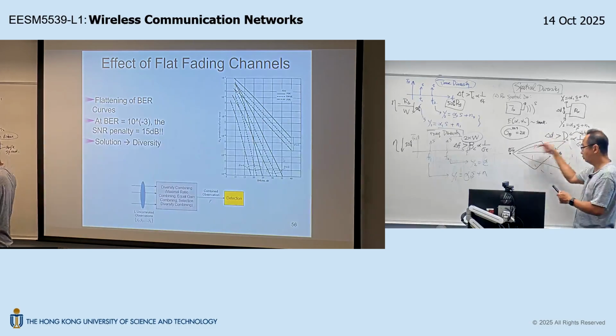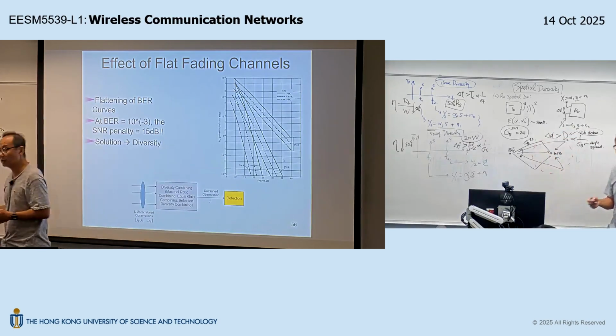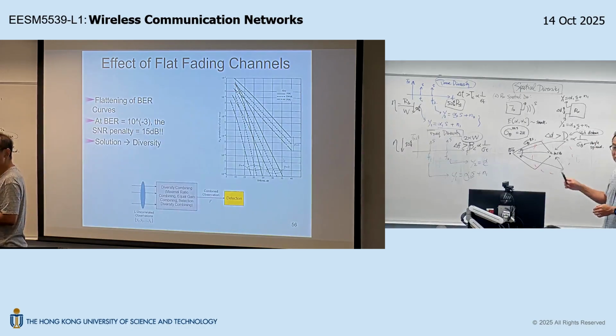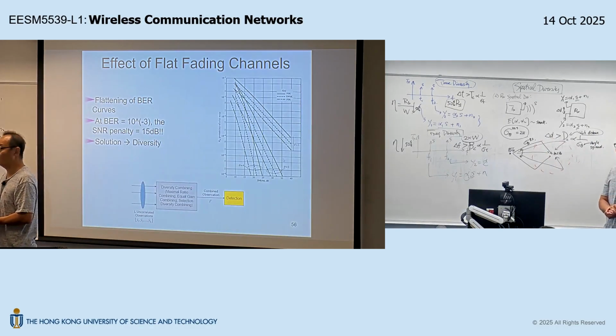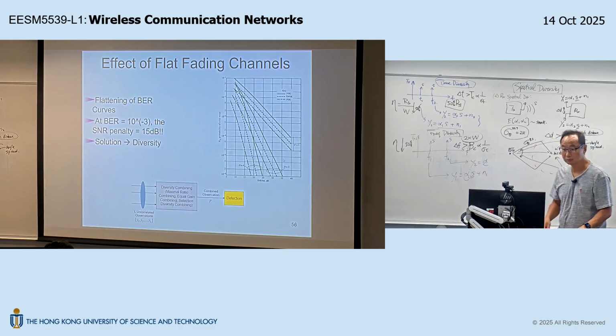In that case, if we reverse the arrow, this is the angle spread at the base station. And the angle spread at the base station is usually pretty narrow. For example, in New York City, they did some field test measurement. The angle spread at the base station receiver side is something around 30 degrees. It's pretty narrow. It depends on the structure of the scattering environment, okay?